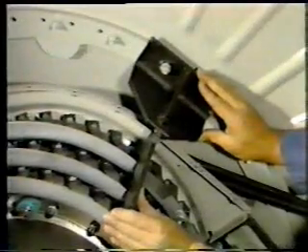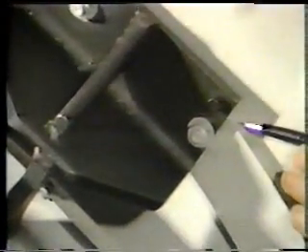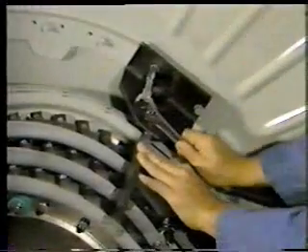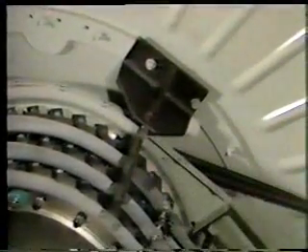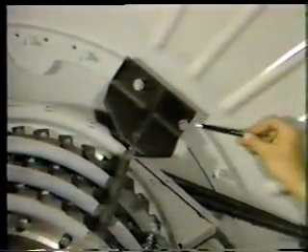Bisect this hole with the upper face of the gauge. Make any necessary alignment adjustments with the gauge and make certain that the dowel pins are resting on the lip of the air inlet housing. Tighten the 2 nuts to hold the gauge in place. Again, check that the dowel pins are resting on the lip and that the edge of the gauge still bisects the hole.